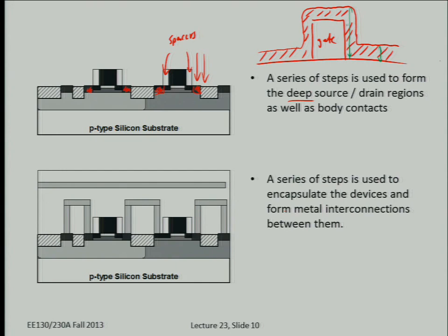So now we can etch anisotropically. There's always going to be some corner rounding during the etch process. Basically you have a directional etch, which we call an anisotropic etch. In other words, it etches faster in the vertical direction than the lateral direction. So you just etch down, removing the thickness vertically. You can clear the dielectric over the gate and in the source drain regions, but you haven't cleared it from the sidewalls of the gate electrode. This is how spacers are formed: you deposit a thin film conformally and then etch back anisotropically.